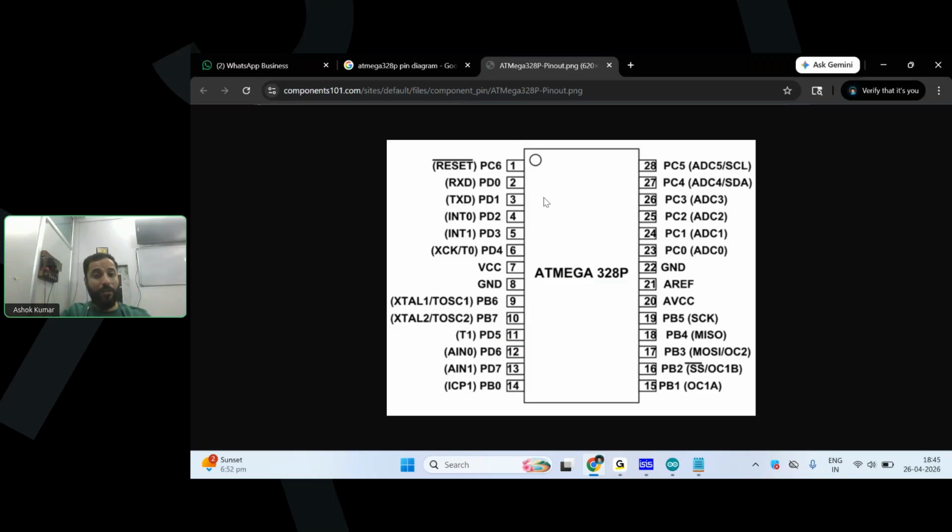You need to understand the concept of PD0, PD1, PC0 when you are programming using the Arduino IDE, because you are actually programming the IC but considering the pin numbers of the Arduino board, right? So you need to remember PD0, PD1. That's how you can do it. PD0 and PD1 are here, receive and transmit, correct? Then pins 2, 3, 4 are here. I guess it's clear now.